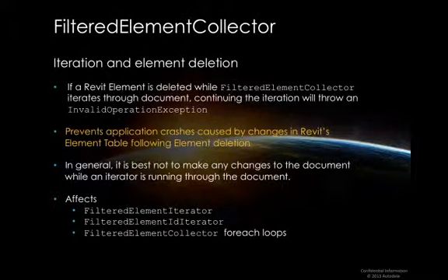One important change has been applied to the filtered element collector. It has always been the case that deleting an element while you are iterating over a collection of these elements can cause unexpected behavior. In 2014, such a deletion will actually trigger an exception to be thrown, so applications that are misbehaving in this way will no longer work. In general, it's actually best not to make any changes at all to the document while an iterator is running.